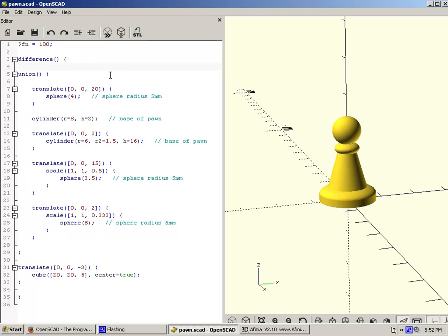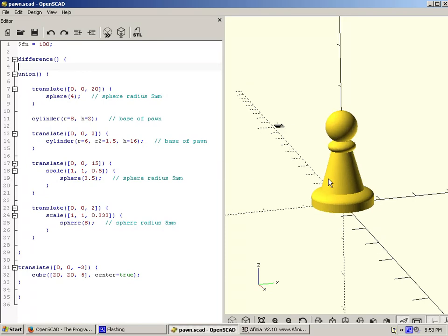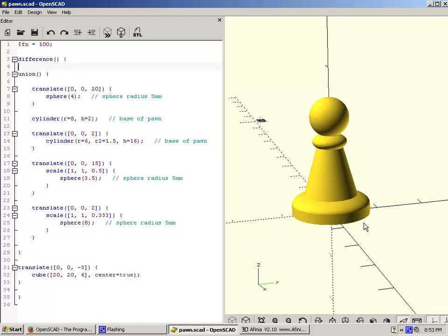You don't have to actually open up, create a new model, and drag around like you would in SketchUp. You can just reuse your code in other models, and very finely tweak it numerically as opposed to clicking and dragging with a mouse. That's really the power of OpenSCAD in numerically describing your shape. In many ways it can make it very easy to tweak various aspects of it very precisely, as opposed to messing around with the mouse and zooming in and tweaking everything around in 3 dimensions, just specifying in code as the alternative.